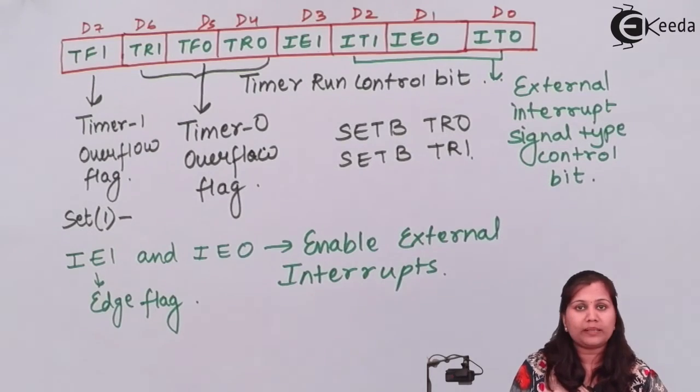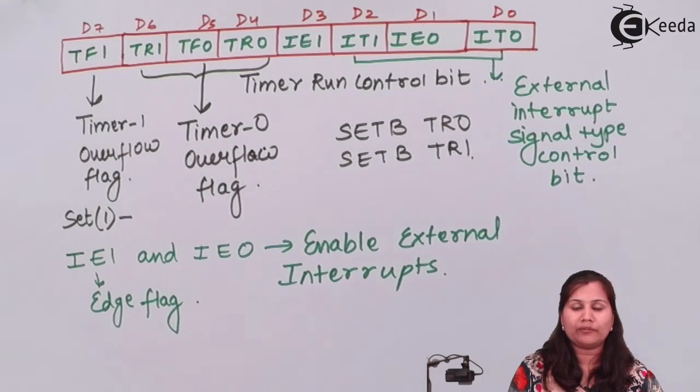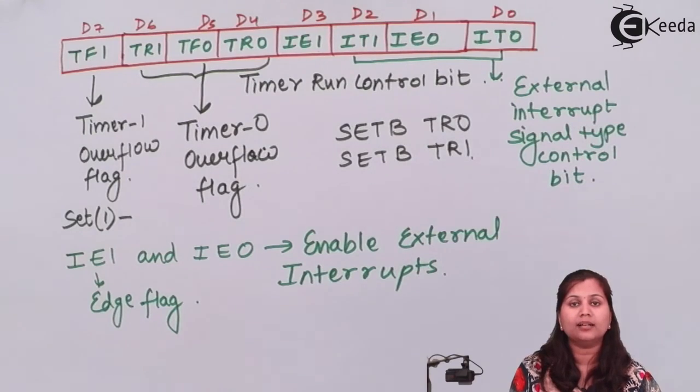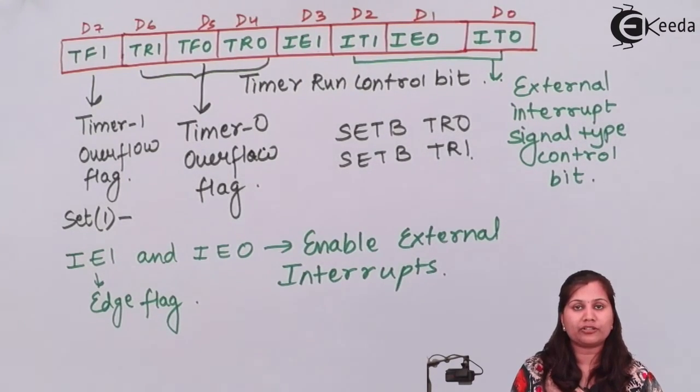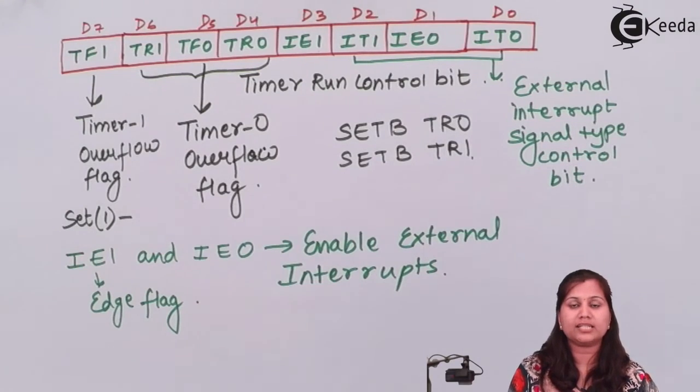In this video, we studied the timers, or we can say counters, of the 8051 microcontroller. We studied that it has 2 timers and counters which can act as a delay generator and also as a counter. We also studied the 2 special function registers associated with them, TCON and TMOD. I hope this topic is clear to you.